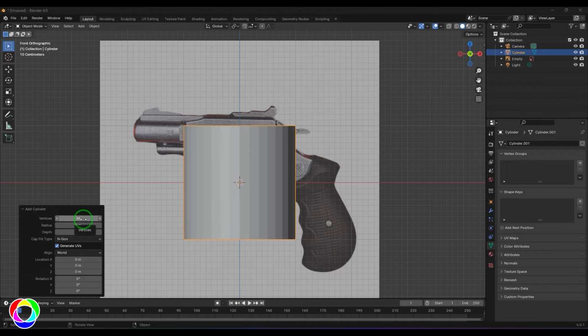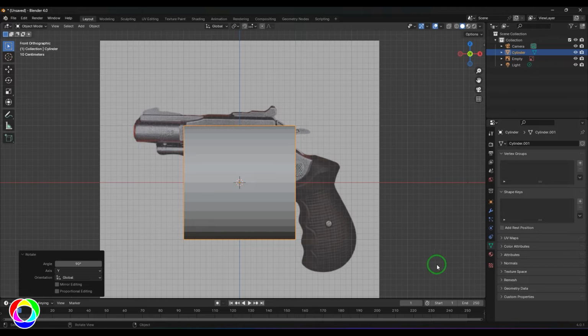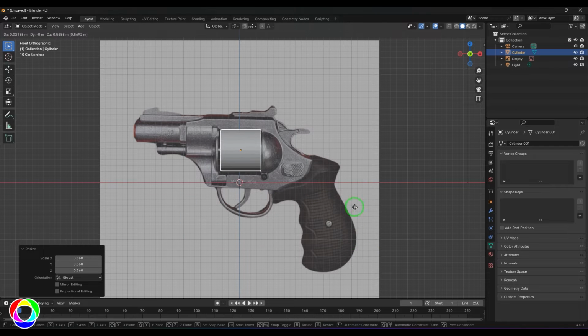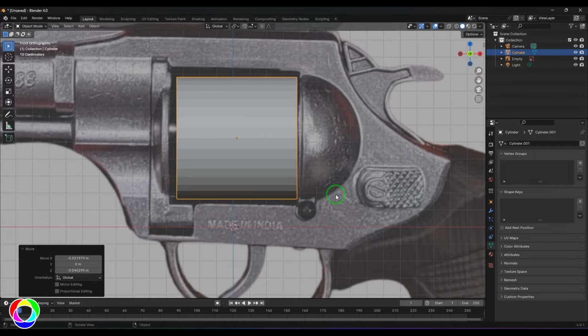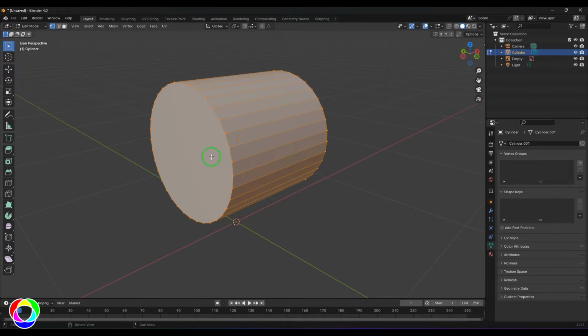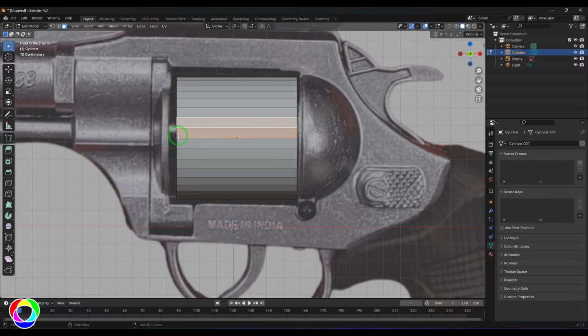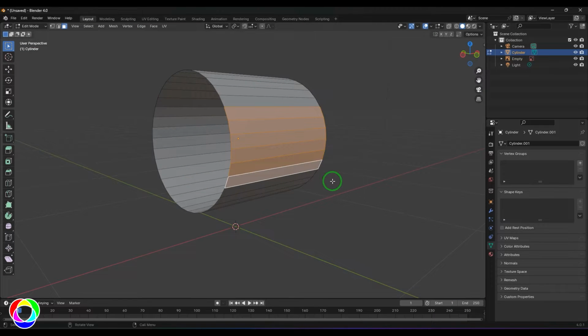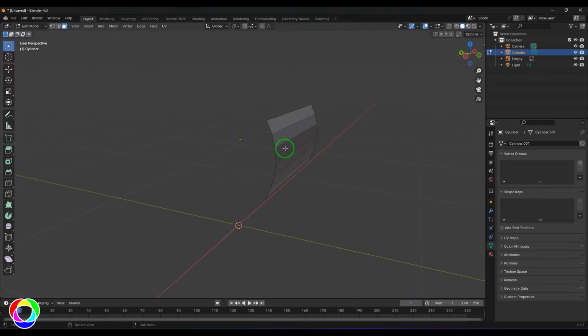So I'm going to choose 36 here. Once that is done, I'm going to choose rotation in the y-axis, then scale it and place that model in the reference perfectly. Okay, so I'm going to select the faces here and delete those faces. Let's say I'm going to select these 2 faces for the ridge, this face on the top, and the bottom 3 faces. So I'm going to press Ctrl I and then delete those faces there. So that's the model here.